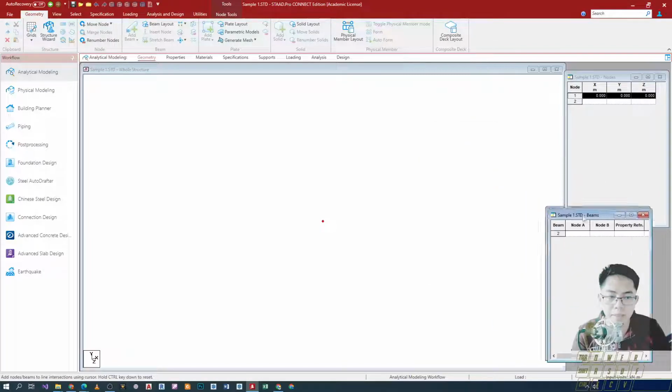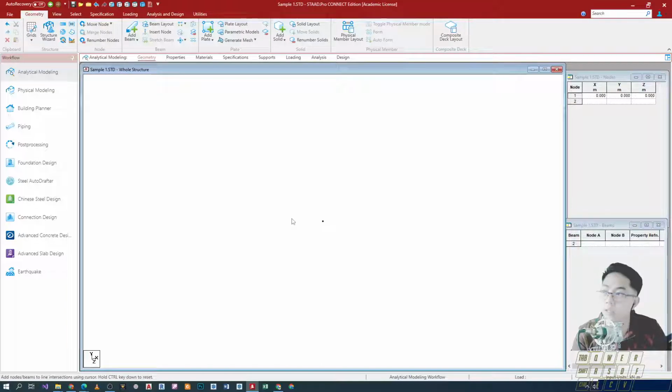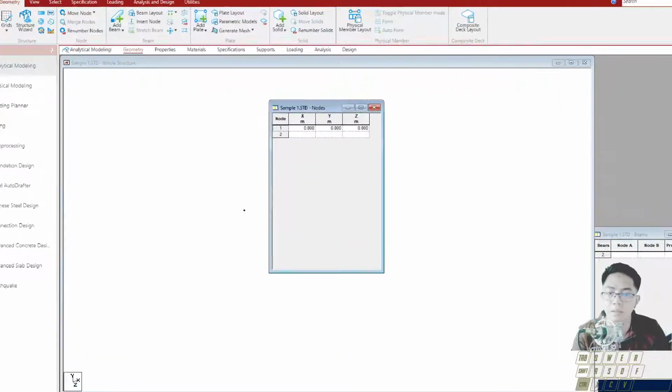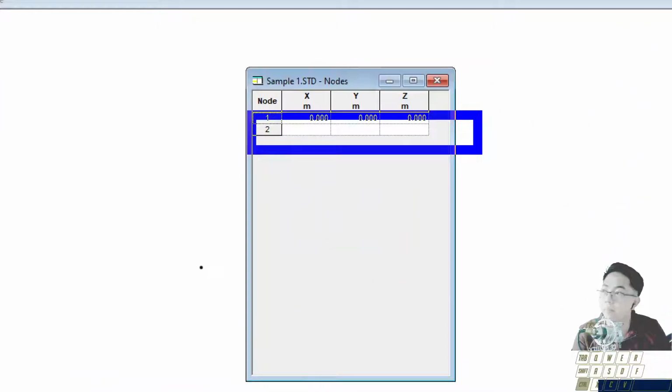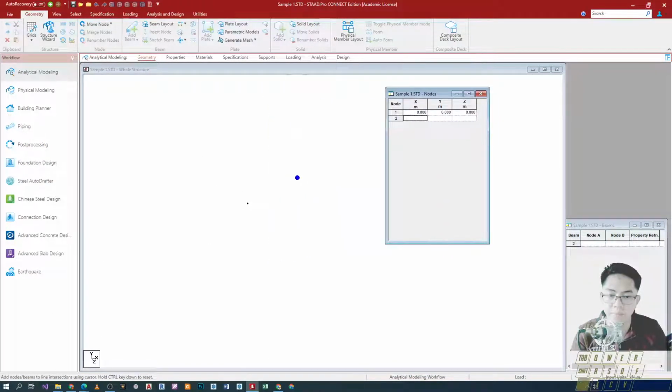Now if we want to replicate the same procedure or the same output as the one we have created previously, what I'll do is go under select, or we can make another joint. We can manually type it here again. So going toward X, right? So 5 meters towards the X direction.